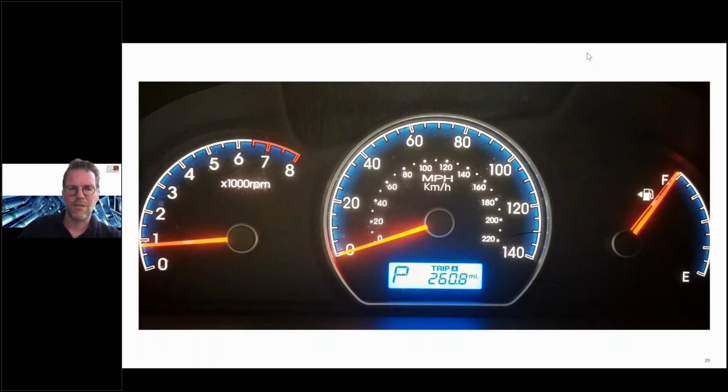You know, it's similar if you drive a car in the city, instead of on a highway. You might have a very fuel efficient car that is efficient on the highway, but it might be less efficient in the city, like electric cars versus gasoline cars, for example. And also you have to take care of your tires, to keep them on the right pressure, to have the friction as low as possible. And we see the same for compressors. So you can have a very nice compressor based on the spec sheet, but in practice, the specific power might be a little off of that.